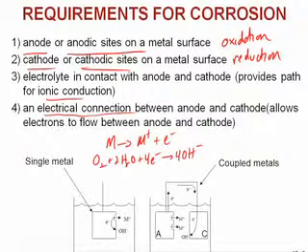That should be a balanced reaction. Okay? And so that's consuming those electrons, creating OH- on its surface. So we have electrons flowing through there, and in fact ions flowing through our electrolyte, completing this circuit. Okay, so there's a complete circuit here for charge to flow. Corrosion is like a battery.